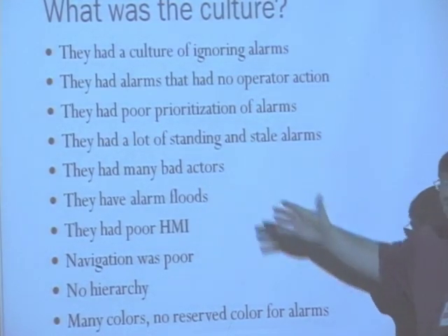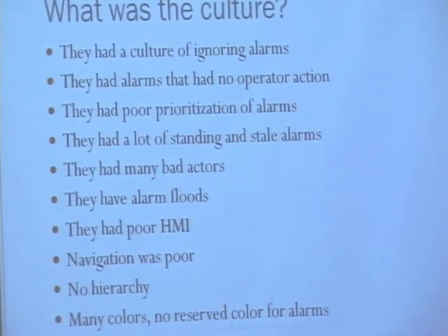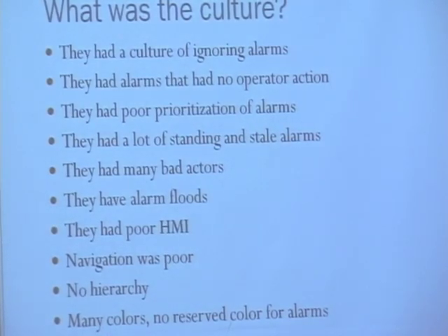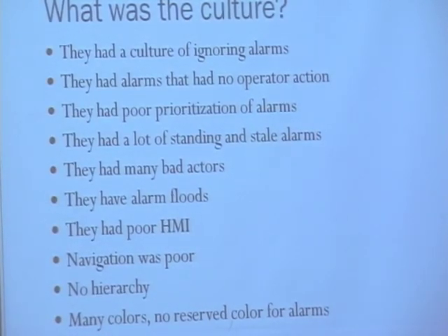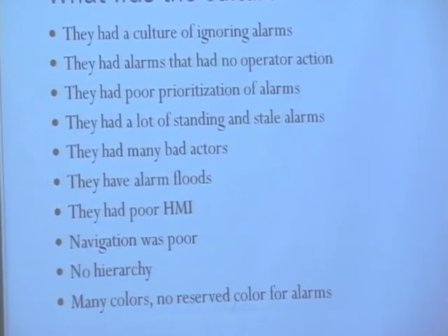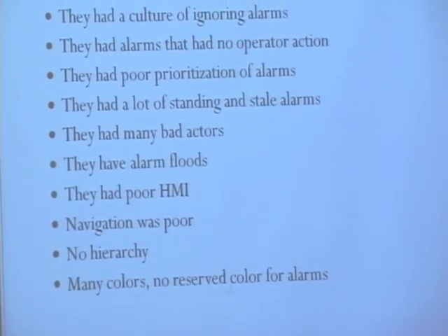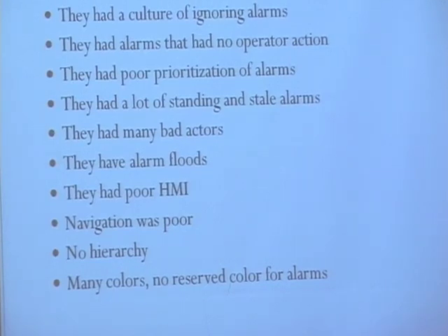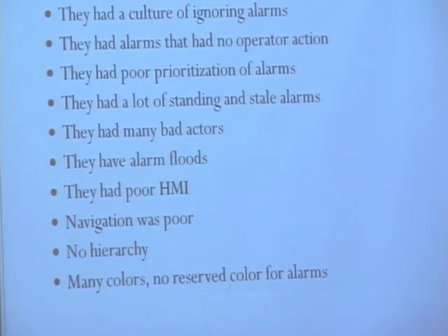They had many bad actors, and I don't mean Clint Eastwood at all. What we mean by that is that there were instruments that were giving alarms that were not useful, okay, at high frequency. And again, a lot of it was either because the instrument wasn't set up correctly or the alarm wasn't set up correctly. Okay, could be fixed.